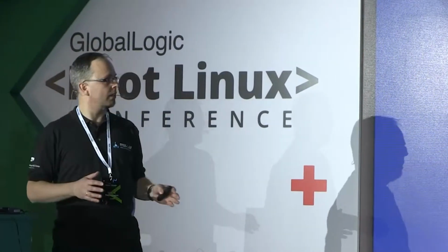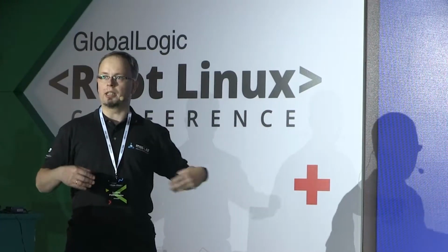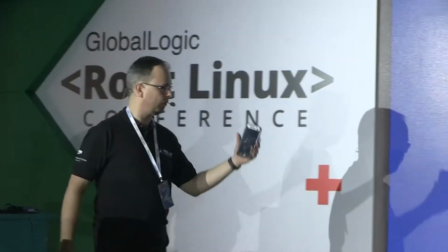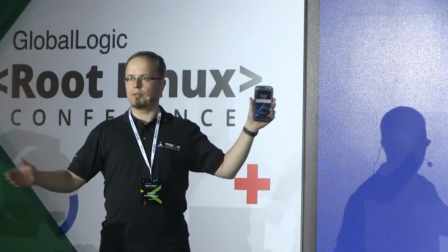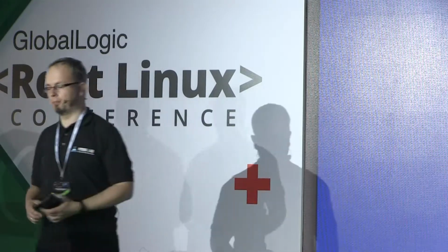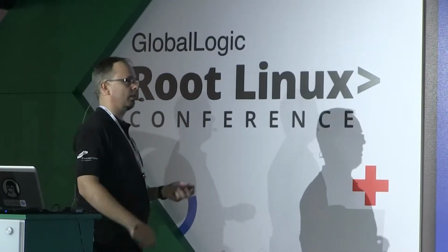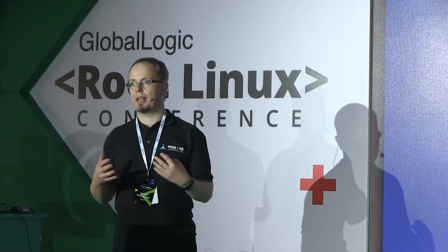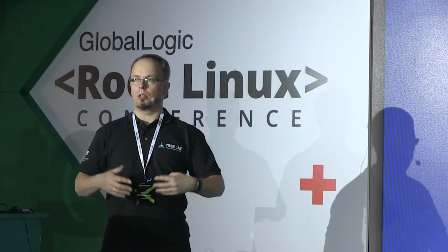Today, our focus is on USB devices which are machines running Linux, equipped with PHY and UDC, and whose actual functionality is implemented in software. Exactly like with your mobile phone, where the way it is seen by the PC is fully software defined. You choose whether you want MTP, PTP, mass storage, or perhaps a broadband modem. So now let's learn something about this software implementation. First of all, the USB standard has no name for this kind of software running on top of UDC. So kernel developers came up with the name USB Gadget.